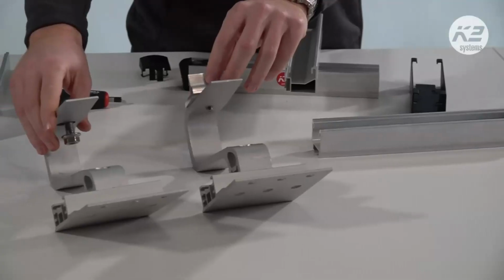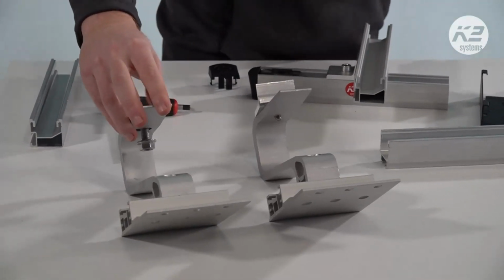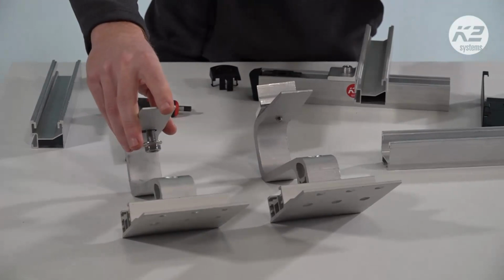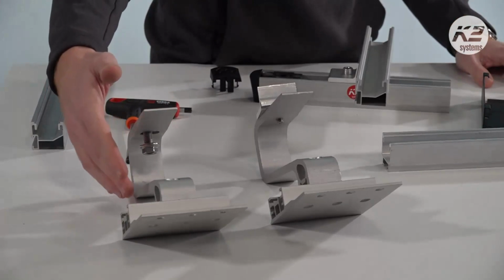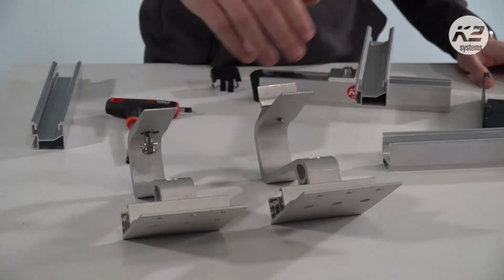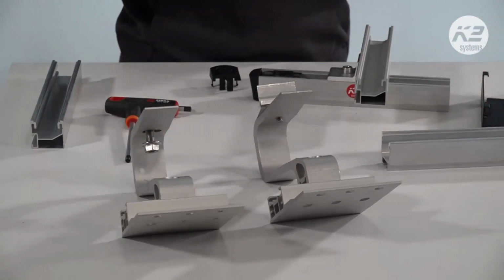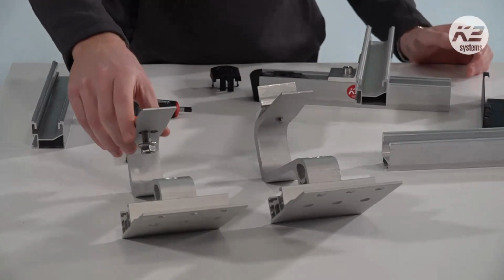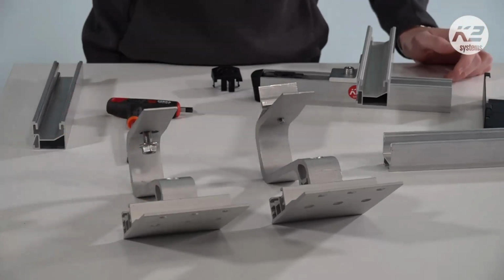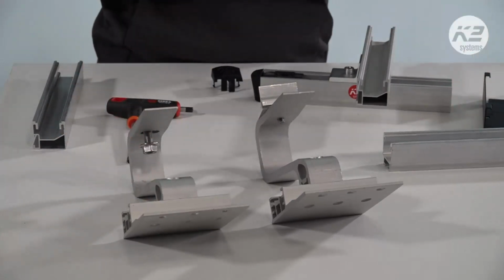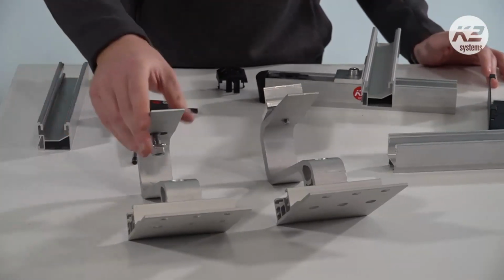Now for both of our hooks, one part is the availability. Which rail do I have available in my stock or on my site? That plays a role. And also, these hooks are aluminum. We also have steel hooks, and the steel hook is usually thinner than the aluminum hook. And this will enable us to cut less of the tiles or of the shingles that we have on the roof.